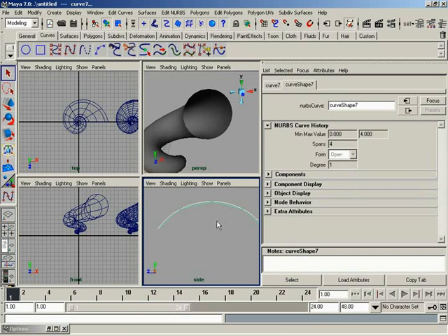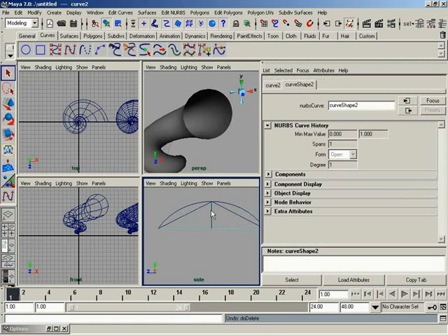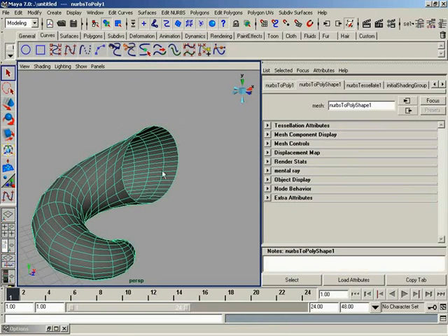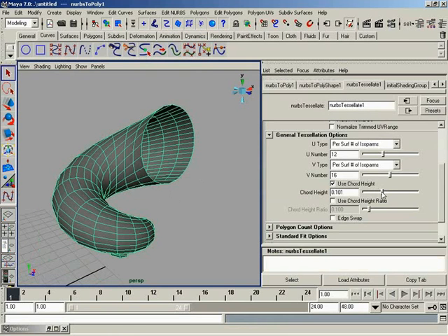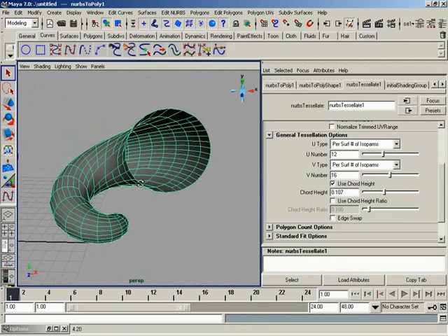I'll go ahead and leave this example here for now. In fact, let me go ahead and undo back to just my original block, like so, because I may need that a little bit later down the road. So that's how chord height is going to work, which also explains why the lower the number goes, the more faces you see. This is also a nice way to control how much tessellation you get at certain points of curvature.